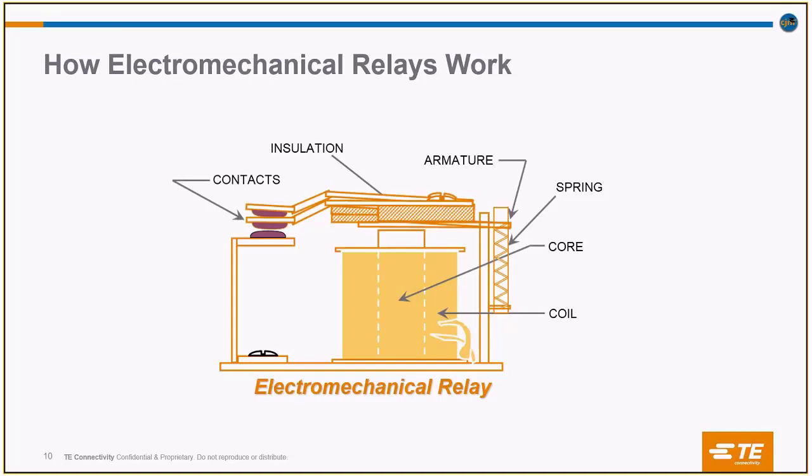So the combination of the insulated iron core over which the wires are wound is known as a coil. Now, the armature. Armature is the moving part or the moving magnetic member of the relay. Armature is derived from the word arms, and arms does what? It supports, right? So the armature here is the moving magnetic member of the relay.